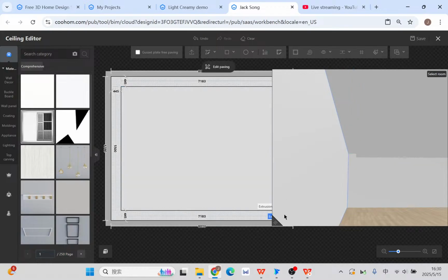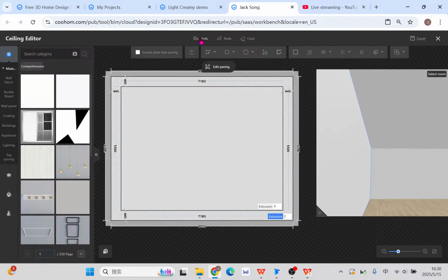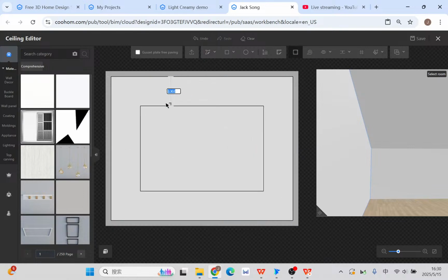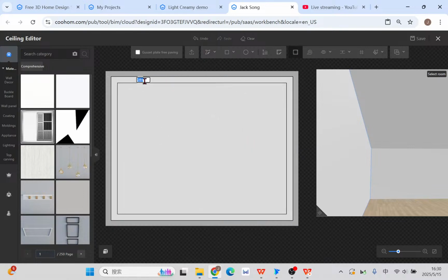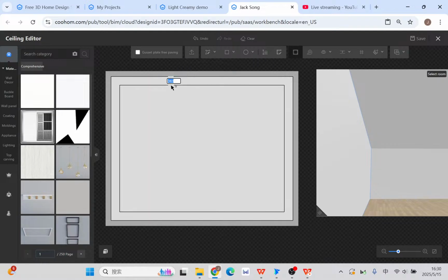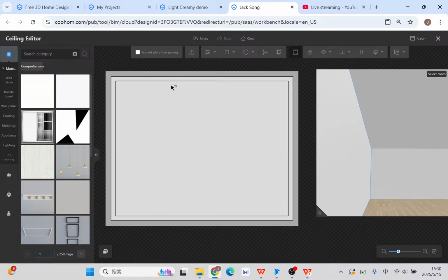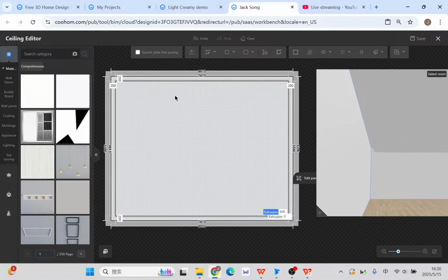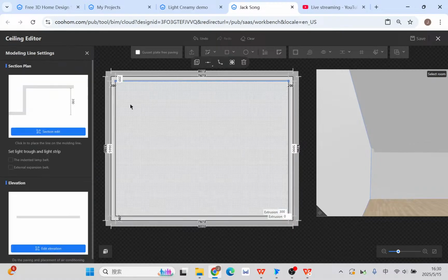And now what you need to do, oh, just one thing I forgot to mention is that the gap between the outer boundary to the inner, you need to limit them. You can't just leave it too big. Sometimes we just leave around 180 or 200, very small. Don't leave too big a boundary. And then set the extrusion still 300. And at this moment, click that.